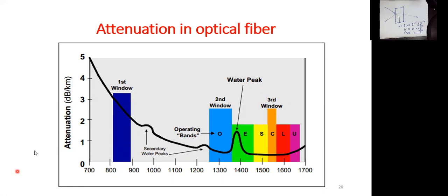Also, as you can see, this region is a visible infrared region, and these two regions are infrared regions. That's why in many optical communication applications, if you come to the lab and disconnect the optical fiber from the terminal side, from the detector side, and look for the light going outside the optical fiber, you will see nothing.